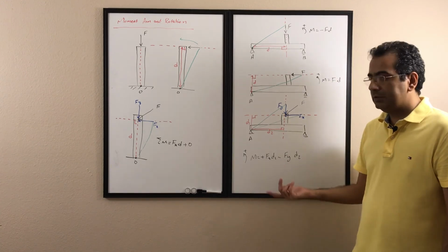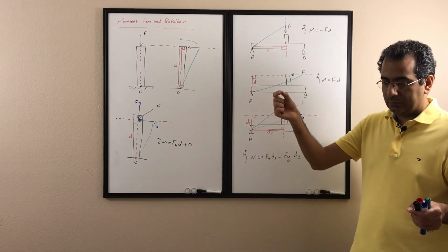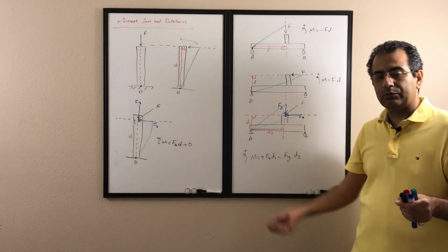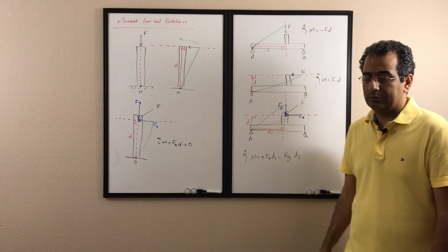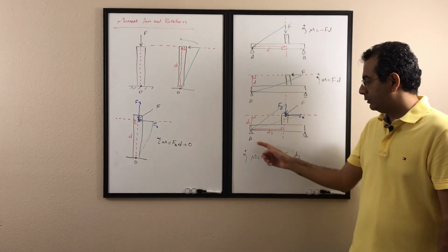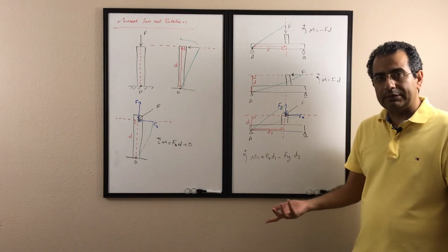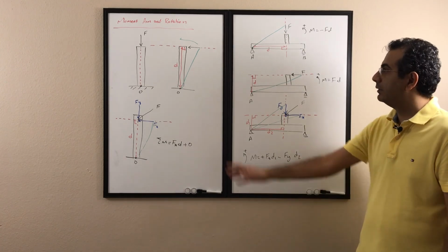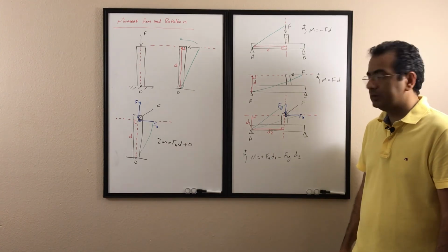And for the rotation, assume there's a rope connected from the point to the force, assume the point is fixed, and see which direction the force is going to rotate that rope. If it's rotating the rope counterclockwise, the moment is counterclockwise. If it's rotating clockwise, the moment is clockwise. Depending on the direction you chose to be positive, you can consider the moment positive or negative. So that's how we can find the moment arm and the direction of rotation for the moment.